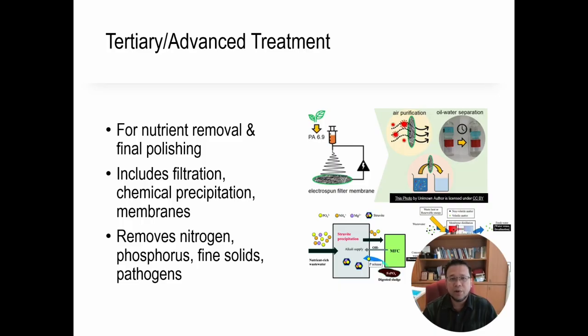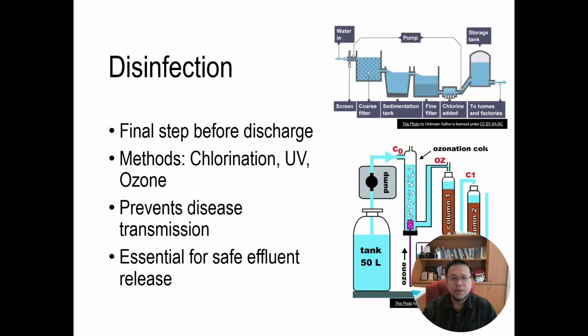Techniques employed include filtration through media like sand, chemical precipitation to remove phosphorus, and advanced technologies like membranes and reverse osmosis. This stage ensures the removal of any remaining fine solids, trace organics, and pathogens to meet stringent regulatory standards.